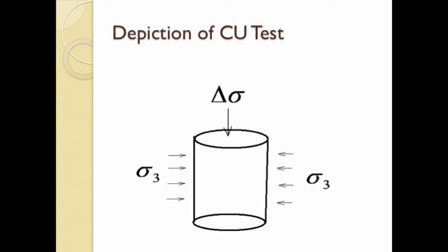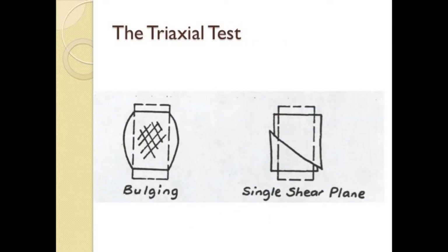The consolidated undrained triaxial test is a measure of soil strength with more realistic field conditions taken into account. A confining pressure is induced on the sample before the test is run, and this acts as sidewall or outer soil pressure, and in some cases hydrostatic pressures. The general concept of the test is to apply an axial pressure to the sample with simultaneous confining pressure. With the confining pressure left constant, the axial pressure is slowly increased until soil failure.